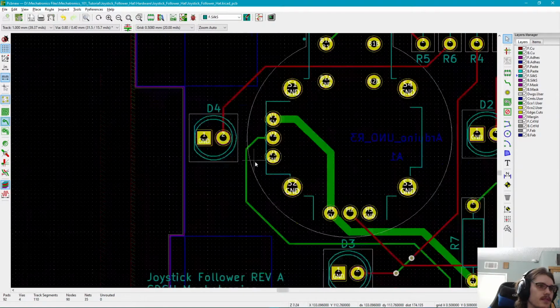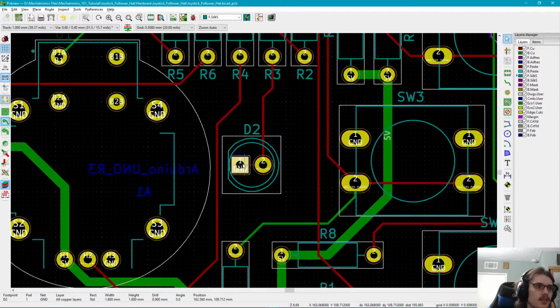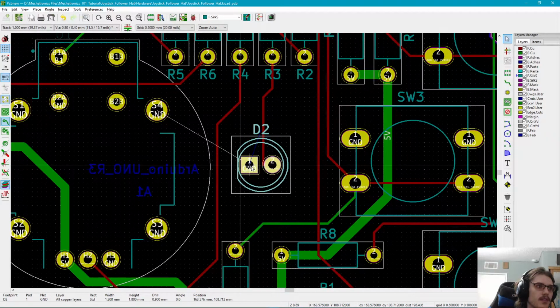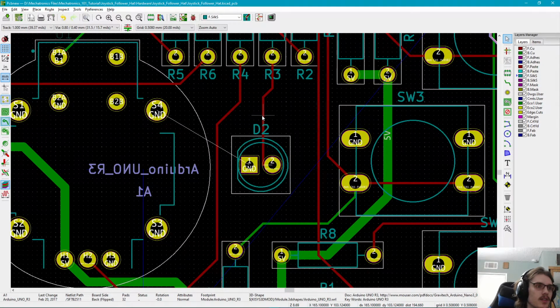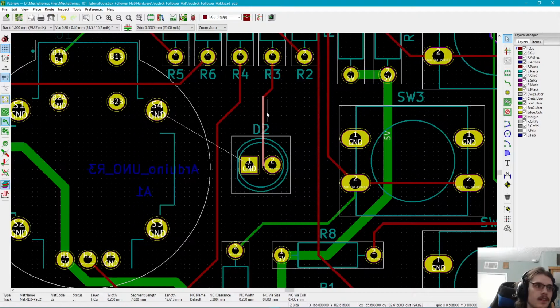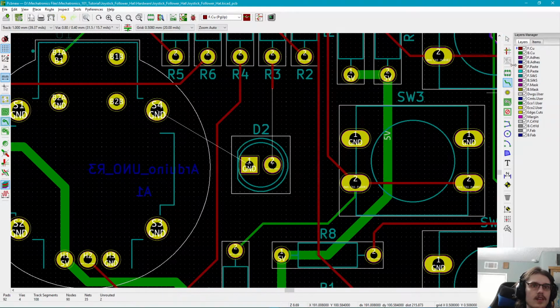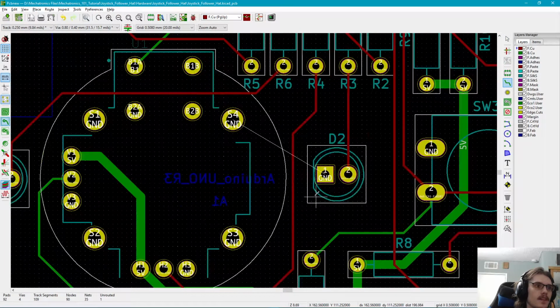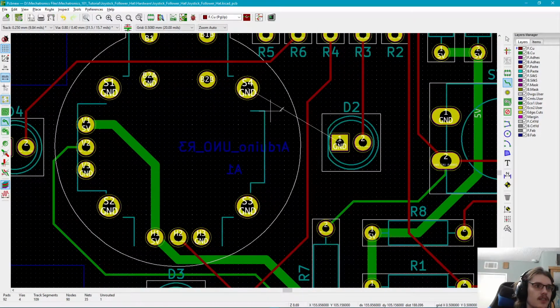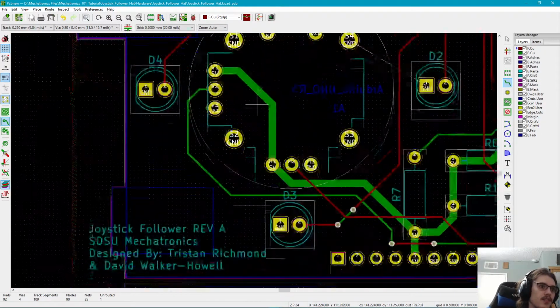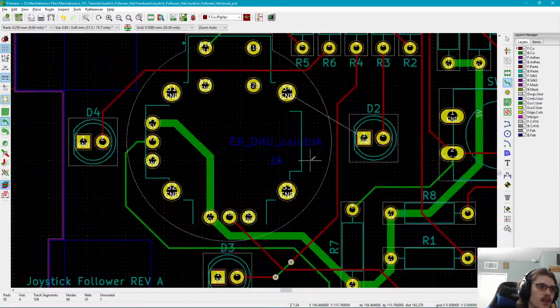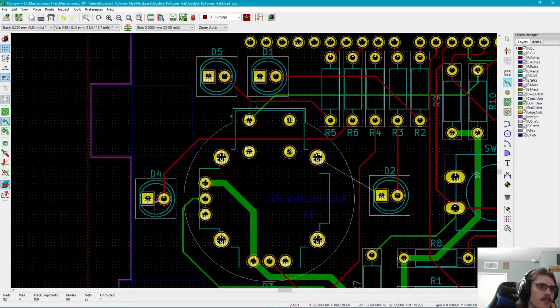We will move this ever so slightly. This is a good thing that I'm actually doing this right here, because it can show you something. Okay, we'll adjust this trace. Look at that, it's even nicer. Oh, not the right track width though. Okay, it's good. As you can see, this ground is now disconnected, and that's because we have to re-pour the ground plane since it was based off of the old setup.